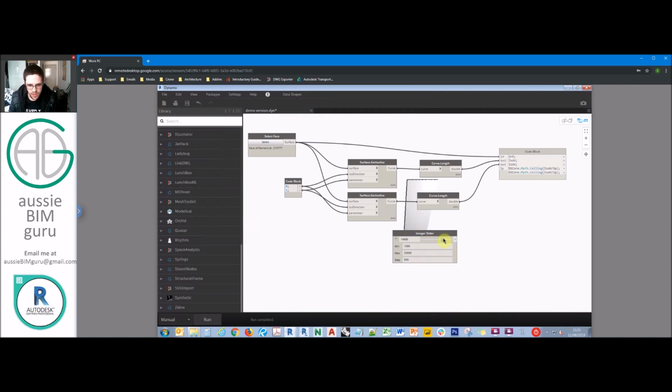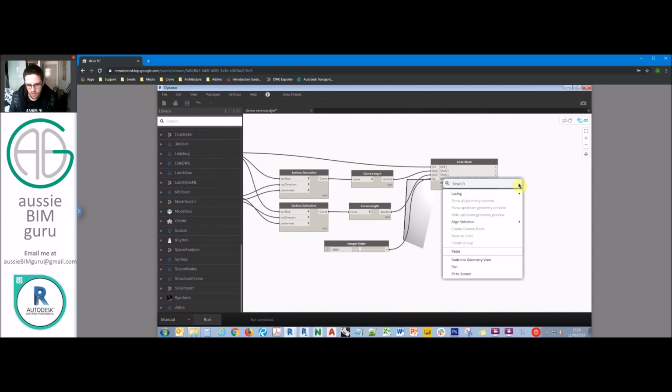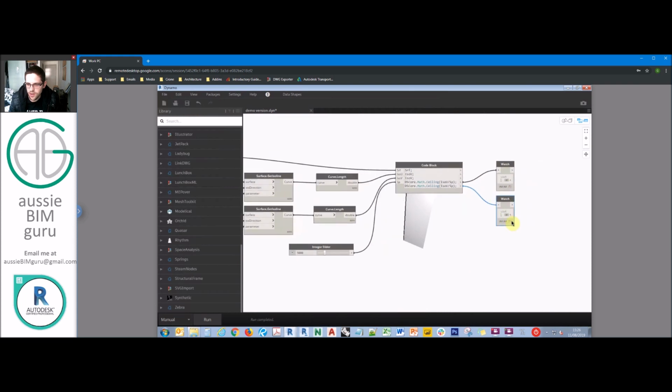That way you can just scale it up like this. And usually I set a default of maybe 5,000. And we'll just feed that into our spacing. So essentially from there we should be able to get a rough estimate of how many U and V divisions we can divide the surface into to get a roughly equal distribution of the spacing. So you can see there we've got 4 by 9, so 9 high by 4 wide. And that's what the ceiling function does essentially.